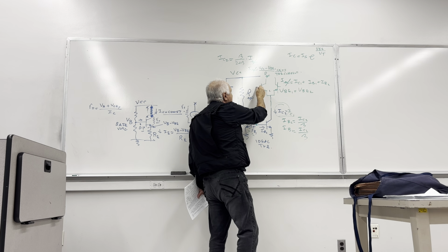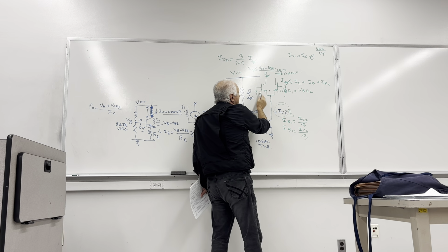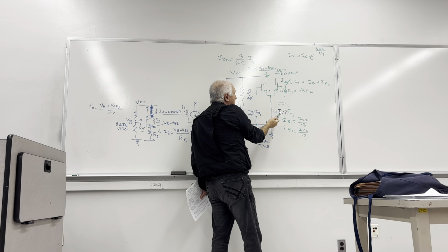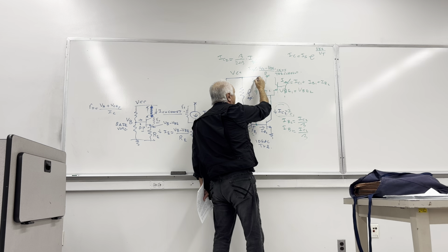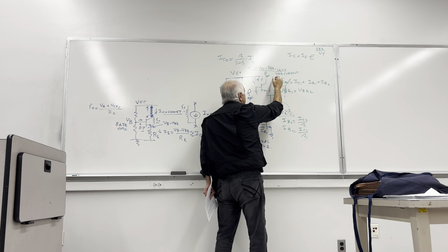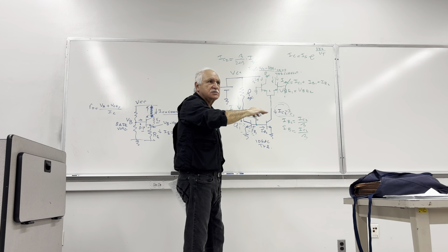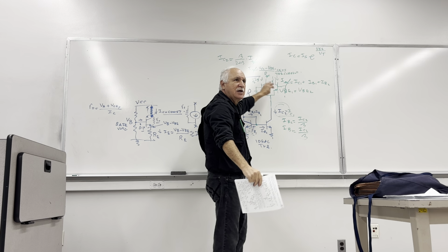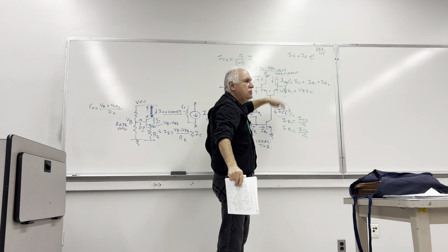And if you connect both grounds, put the base to the ground, again, VBE of this identical to VBE of that. So what you will have, this current, half of it will go into here, 1/2 of Iref, the other 1/2 will go into here. It's coming forward. Let's take a little time, we'll get there. But it can go anywhere. It can go to a resistor, wherever you like.